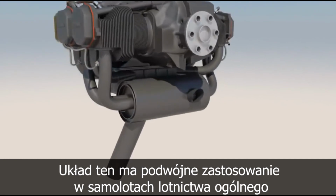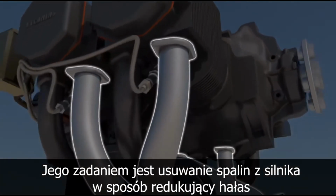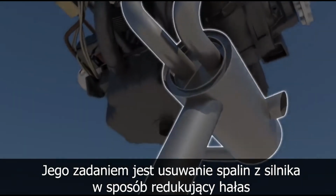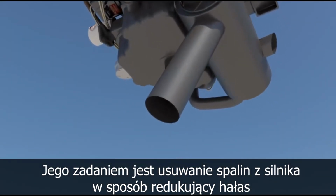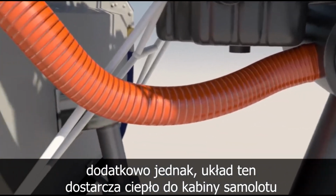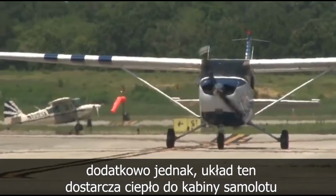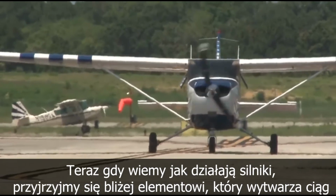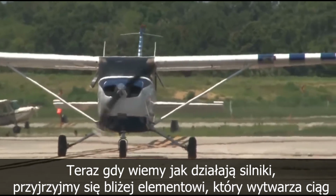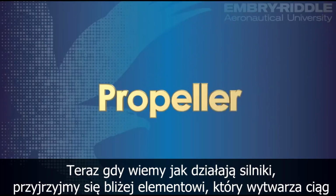The last step in the four-stroke cycle is the exhaust. The exhaust system has a dual purpose in most general aviation airplanes. As expected, the exhaust system does allow the hot exhaust gases in the cylinder to escape the engine in a quiet manner. Additionally, as we'll talk about later, the exhaust system also provides heat to the cabin. Now that we have a better understanding of how an engine basically works, we will examine what creates the thrust for the airplane to fly.